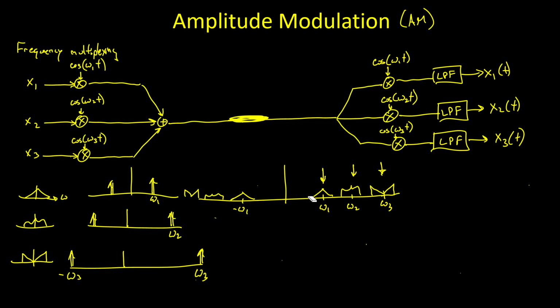When we convolve this by our omega 1 again, this will be a little bit hard to draw, but we'll get this entire thing moved to the left. So that will look like, and this will be pushed off at minus 2 omega naught. And then this right one will be copied over here. So that's when it's convolved by this left guy.